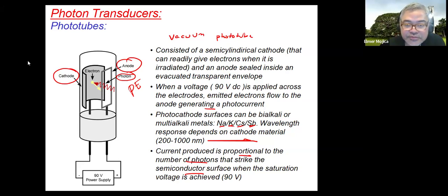The way you look at it, you have a phototube with a photosensitive cathode, then you have an anode, and a vacuum-filled space. That's why some call it a vacuum phototube. When the light photons strike the photosensitive cathode, they eject electrons through the photoelectric effect, and these emitted electrons are accelerated toward the anode by an electric field, resulting in a measurable current.